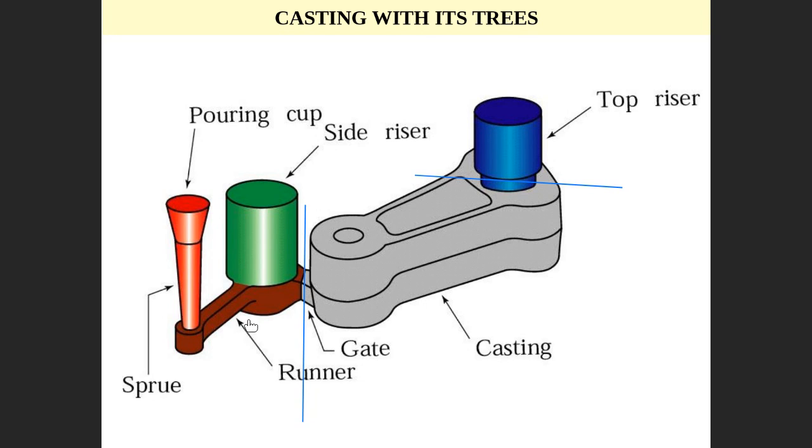Unavoidable. You must have it. You must have the sprue, pouring basin, you have the runner, and this kind of thing. This detail must be there to bring the liquid inside. You must create this channel to bring liquid inside, and the open riser as well. So it is unavoidable to have this kind of additional material. And you need to cut it, and probably you recycle. Recycle means you put it in a furnace, you melt it and reuse it later to create another part, right?